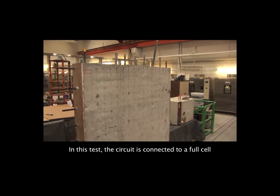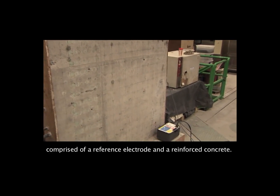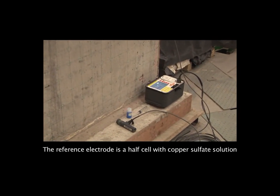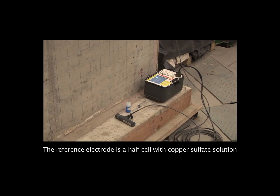In this test, the circuit is connected to a full cell comprised of a reference electrode and a reinforced concrete. The reference electrode is a half cell with copper sulfate solution, and the reinforced concrete is the other half cell.